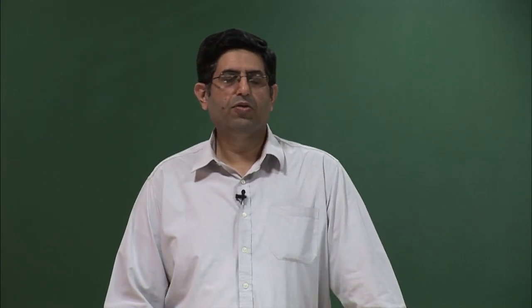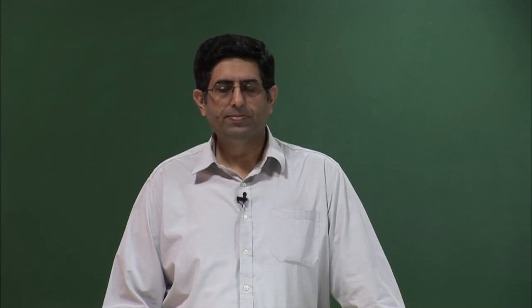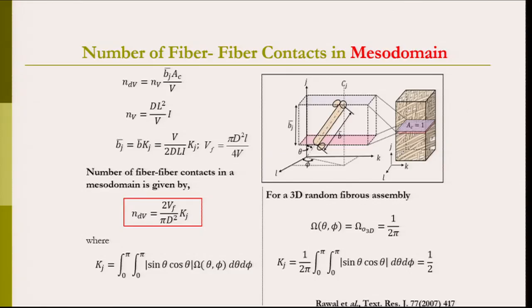And in this part of the lecture, we are going to talk about how we can apply the theory of fiber-to-fiber contacts in predicting certain mechanical properties. We have shown this slide in the last part of the lecture. As you can see here, we have understood the method to calculate the number of fiber-to-fiber contacts in a mesodomain based upon the total number of fiber-to-fiber contacts in a defined volume.